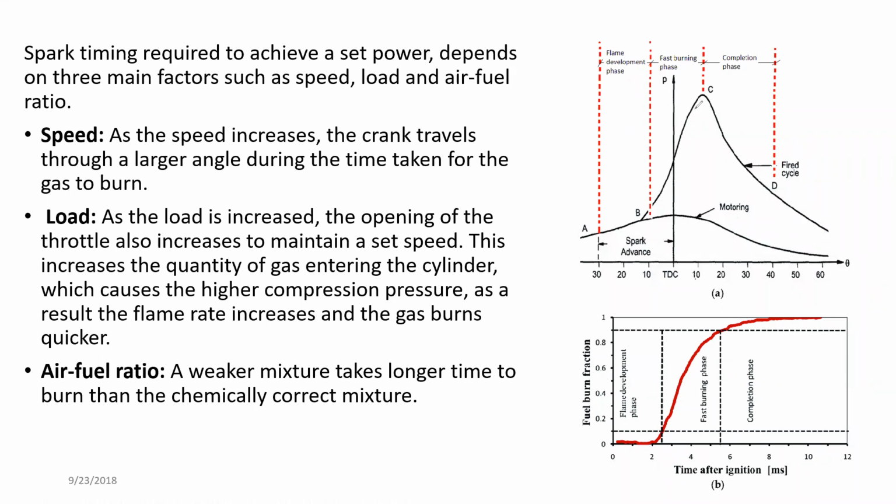So usually, as I told you, the maximum pressure inside the combustion chamber should reach between 10 to 15 degrees after TDC. In order to meet this particular time, this spark time and the complete burning time, or this fast burning phase, is very important.